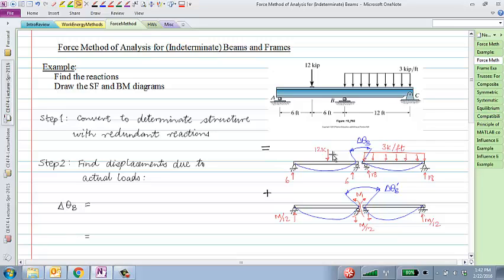So which clearly is something like that, right? And what this table tells me is that the maximum displacement is PL cube over 48 EI at x equals L over 2, which is in the middle. And the maximum rotation is PL square over 16 EI, of course, at the ends. So this is something that I'm sure you can calculate by using any of those methods, but it's just easier, of course, to make use of these tables whenever we can.